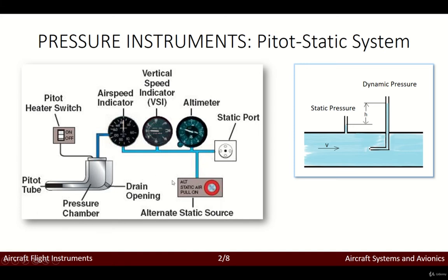Both openings in the pitot tube need to be checked prior to any flight in order to ensure that neither is blocked, right? So what else? Many aircraft have pitot tube covers installed when they sit for extended periods of time. This is done as a way of making sure that the system will endure over time with no real problem. This kind of approach actually helps to keep bugs and other kinds of objects from becoming lodged in the opening of the pitot tube.